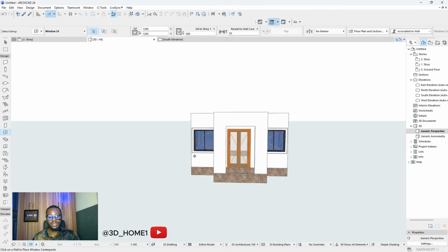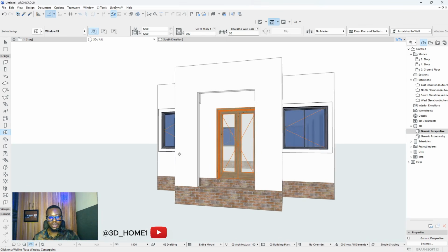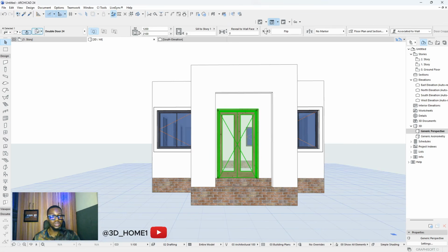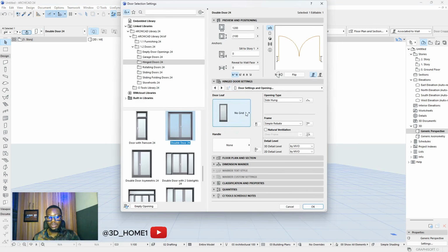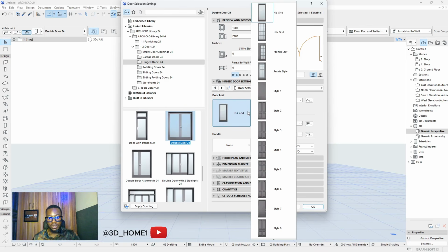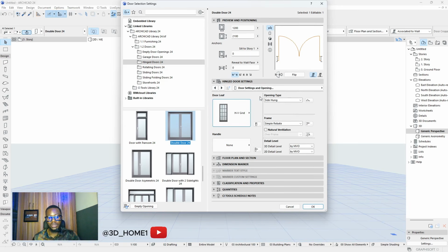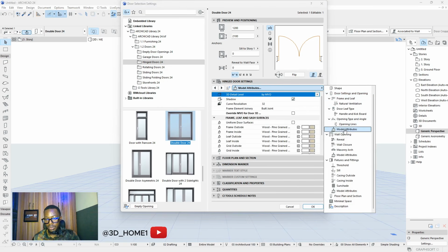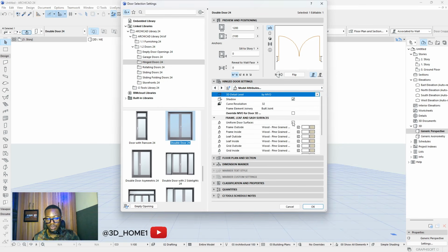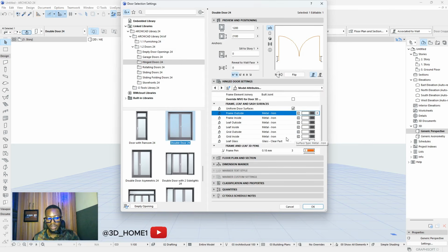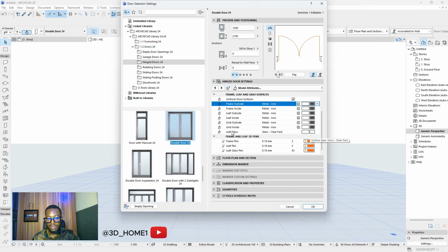So now how about the door? Can we change the door? Yes, we can change the door. Click on the door. Go inside, where the model attribute is. Just click here. Any need of adding some? Okay, let's add grid. I click on this one and change here. Let's change the wood to metal. I do have glass, yes. Glass.